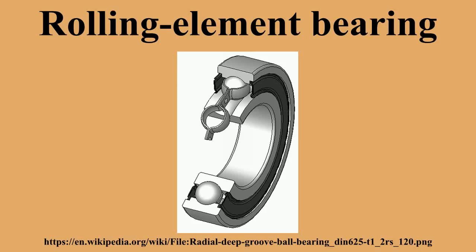Gear bearing is a roller bearing combining two epicyclical gears. Each element of it is represented by concentric alternation of rollers and gear wheels with equality of roller diameter to gear wheel pitch diameter. The widths of conjugated rollers and gear wheels in pairs are the same. The engagement is herringbone with the skew end faces to realize efficient rolling axial contact. The downside to this bearing is manufacturing complexity.